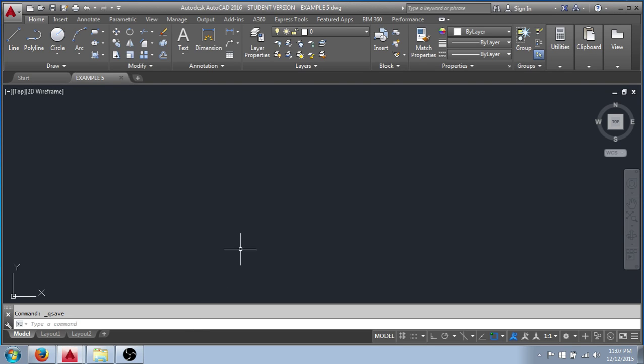What you'll find with that is when you're zooming or panning your work, you'll hit what I call the zoom wall, and it's not going to let you zoom in or out as far as you might want to, or pan as far around on screen as you might want to. It'll get stuck, so to speak. And so what we'll do to prevent that kind of stuff is we're going to set our limits.